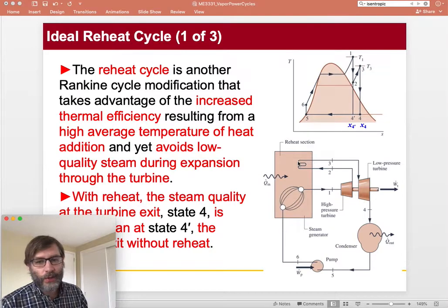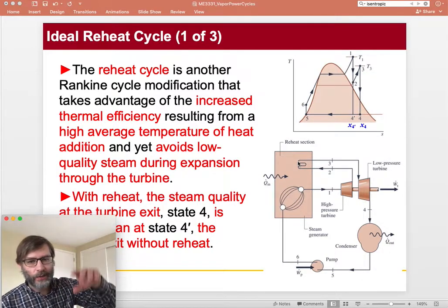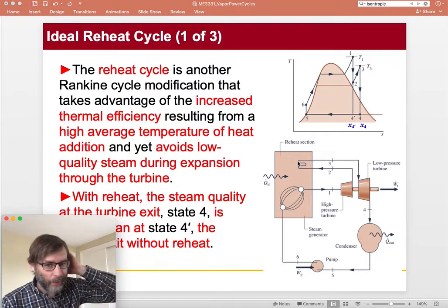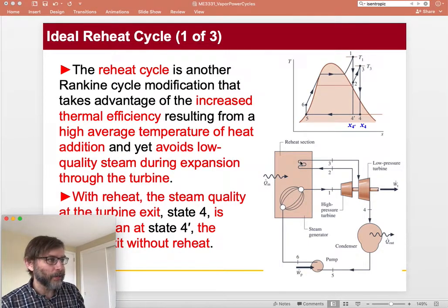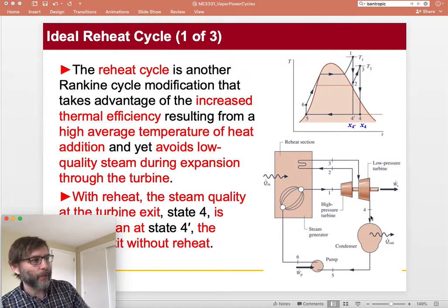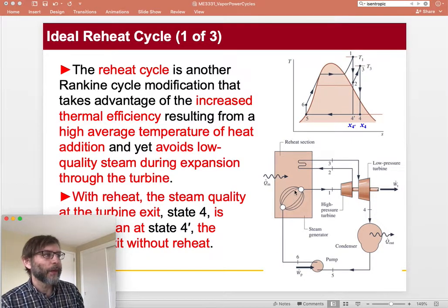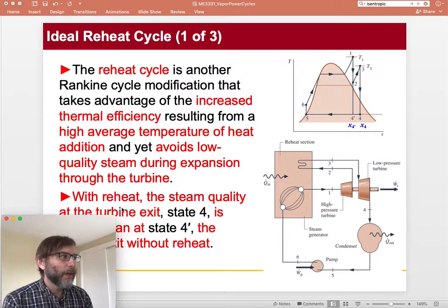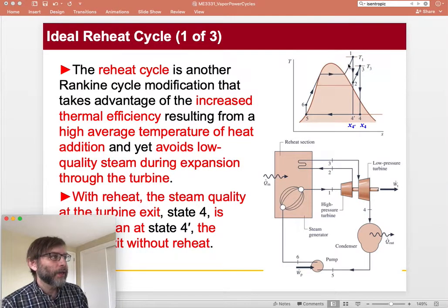The reheater is just another set of tubes inside the boiler box, way up high, where it reheats the steam coming out of the high pressure turbine, and then sends it into a low pressure turbine, which is usually a bigger machine and makes more power. Then from there, you expand it down below atmospheric pressure into the condenser and then into the pump again.